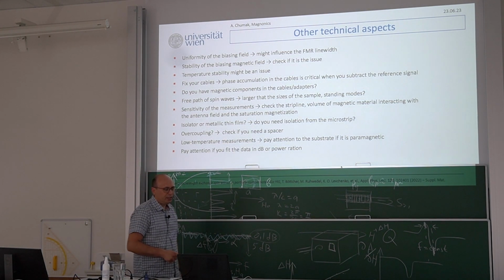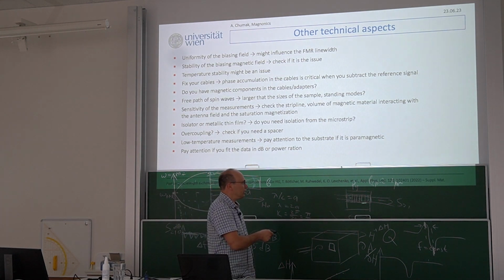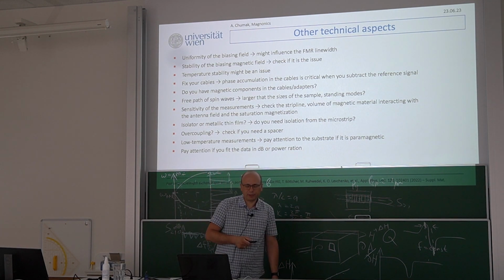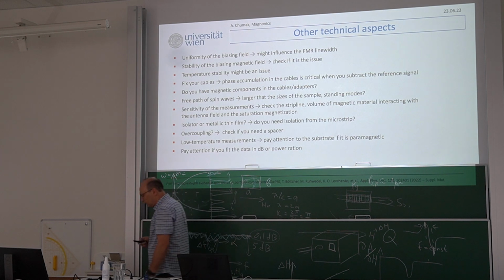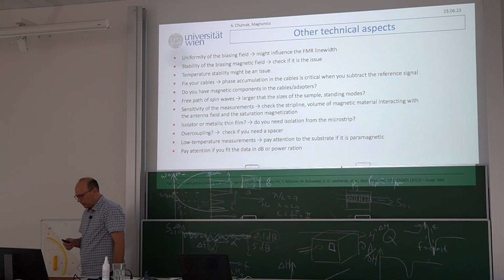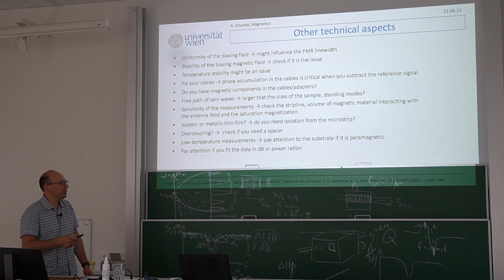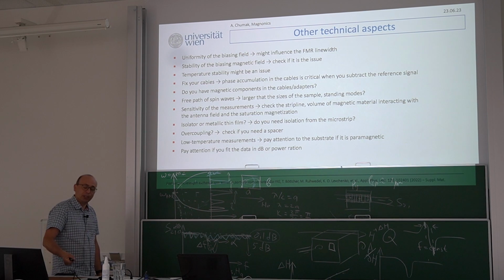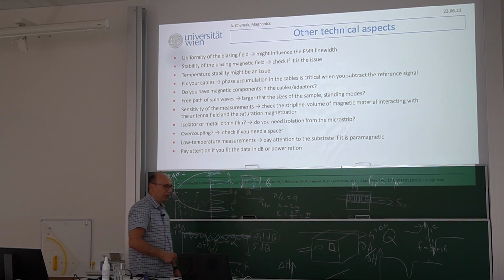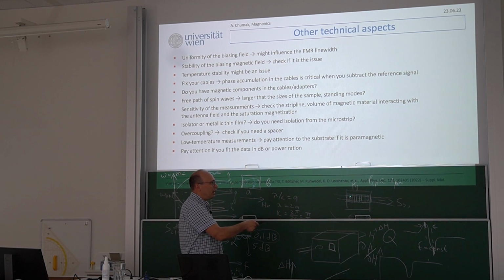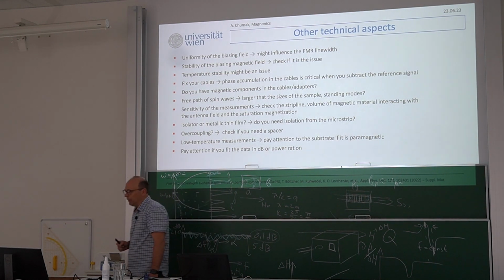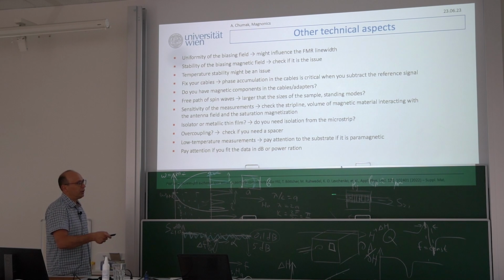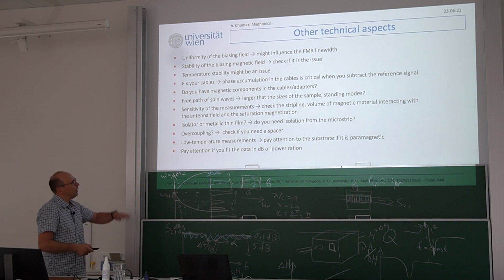In some cases like yttrium iron garnet, metallization is not a critical issue for you, but what is important is that the metallization might change damping. Therefore, simply your damping on the metallized part and here might be different, not necessarily, but might be. Also think if you want to put some insulator layer in between.